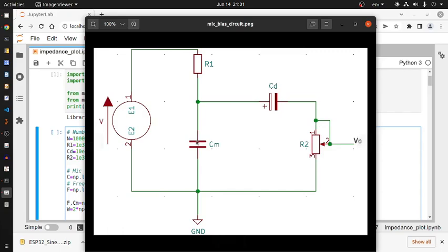So what is the working principle of the mic condenser? Once the input sound wave comes to the mic condenser surface, it changes the distance between the two diaphragms. In between there is a non-conducting material, so the capacitance of the microphone changes, and therefore there will be some voltage fluctuations across this capacitor. That fluctuation is carried through the rest of the circuit.